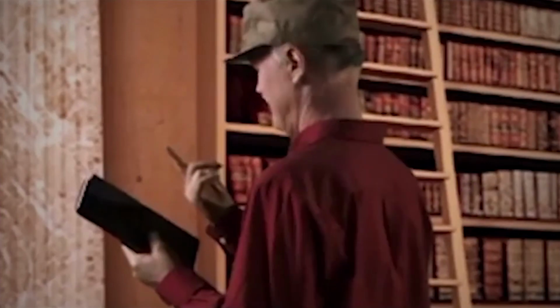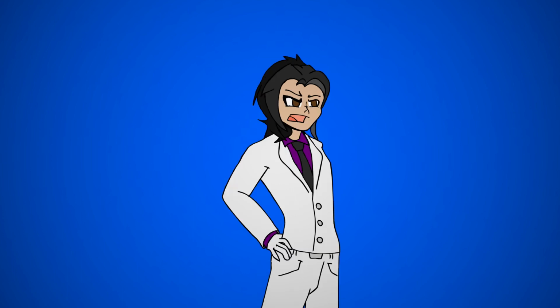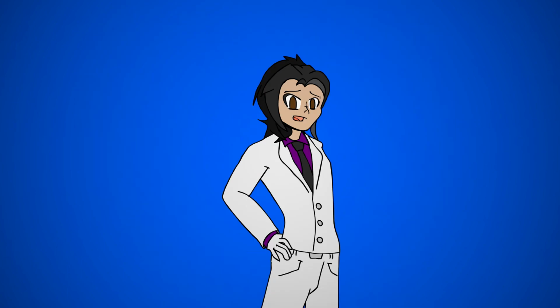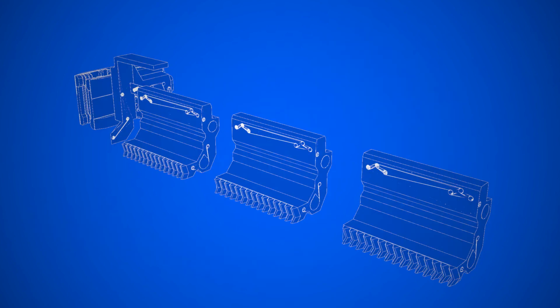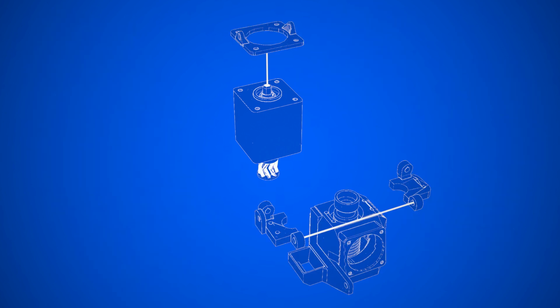You have to do so much maintenance with belts, like tighten them and make sure they don't wear out and replace them. No belts. So to achieve this, I'm going to put the stepper motor on the hot end itself and move the entire assembly across the linear rail that has the teeth gearing in it. I'm going to have 2 metal supports in it, 1 drill rod and 1 smooth rod. I do not have video of this getting assembled because once I assembled it, I was not going to take it back apart for this video.